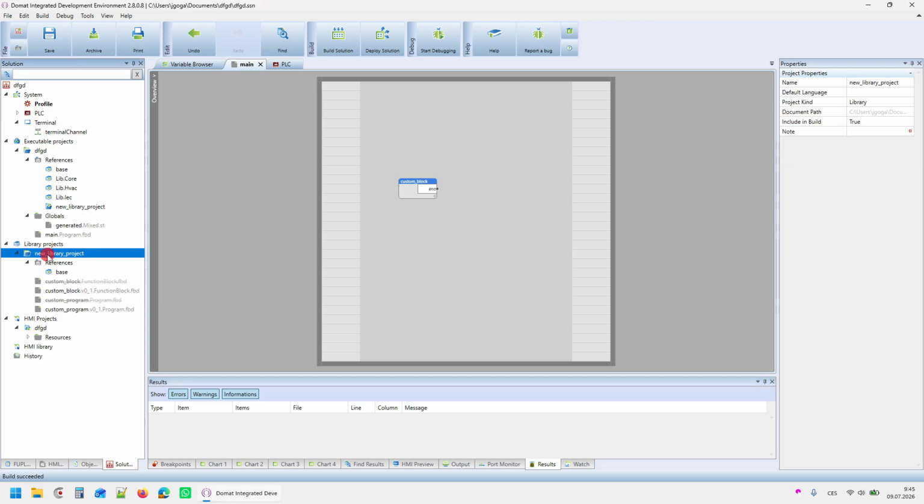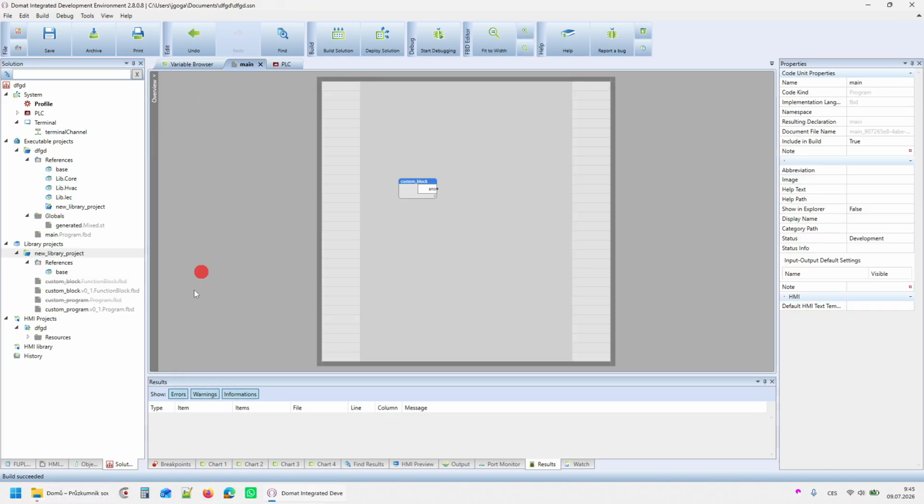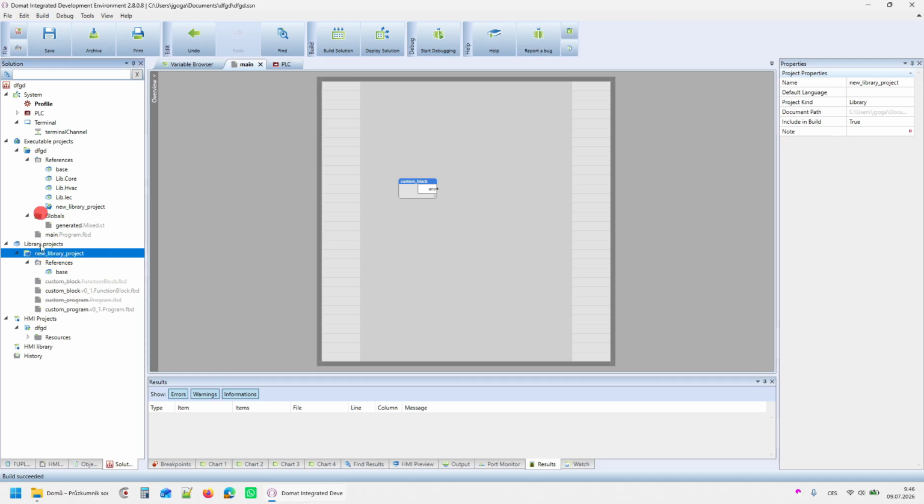If you map the library project remotely and then you want to send this project to someone and you would only send this folder, he would see that the library project is missing. So either I have to remember that and send him the folder with the library also with the program, or I can copy the folder inside this project folder and map it not remotely but from this local folder.